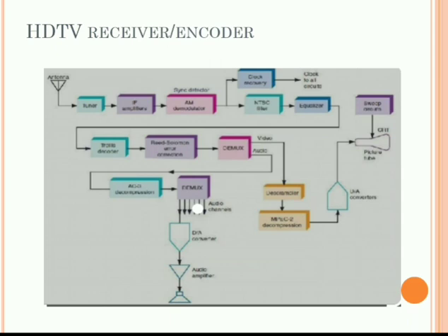The trellis decoder and RS decoder here in the receiver block ensure that any errors caused by noise are corrected. They are captured by that decoder and then corrected by using the correction circuit. Noise or extra elements are added in the channel. The signal at the output of this decoder is then descrambled and decompressed.